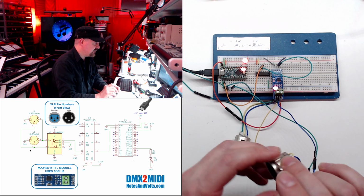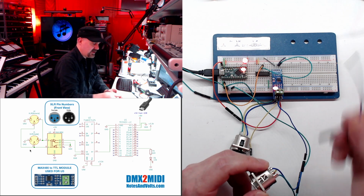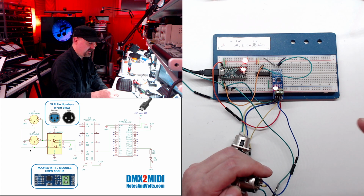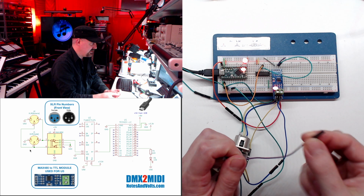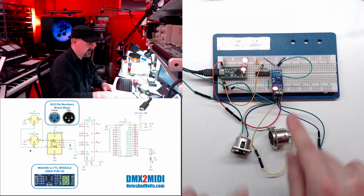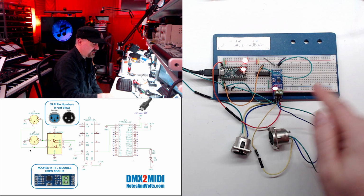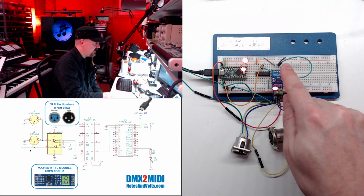Now, to make these jacks a little easier to work with while I'm breadboarding, I once again got these male to female cables, and I cut the male end off and then basically soldered it to the jack. So now I've got this and I can plug it into various things. Now we have power and data going into our little converter board here. It's going to do its conversion and spit out 0 to 5 volt TTL logic signals out